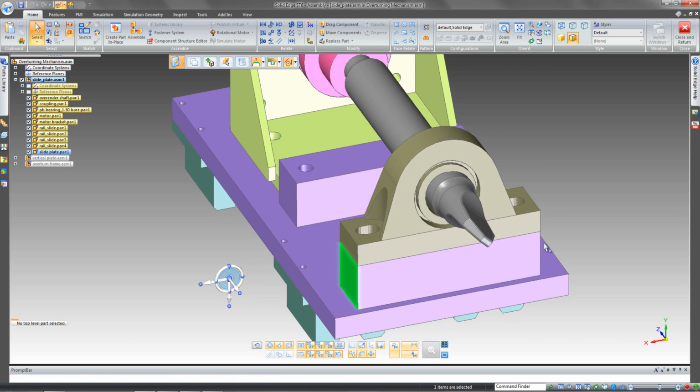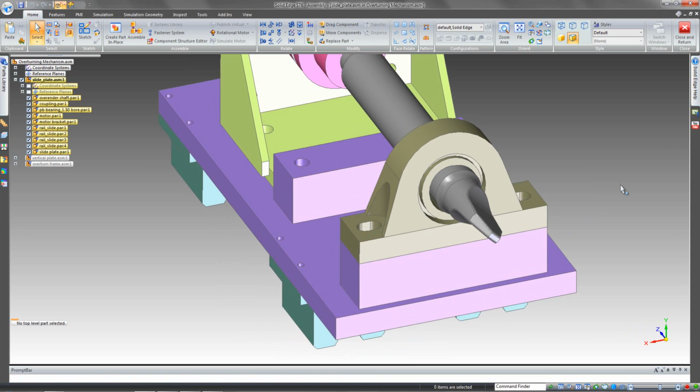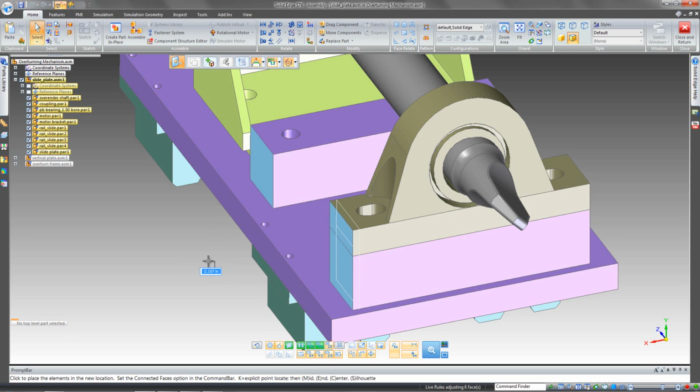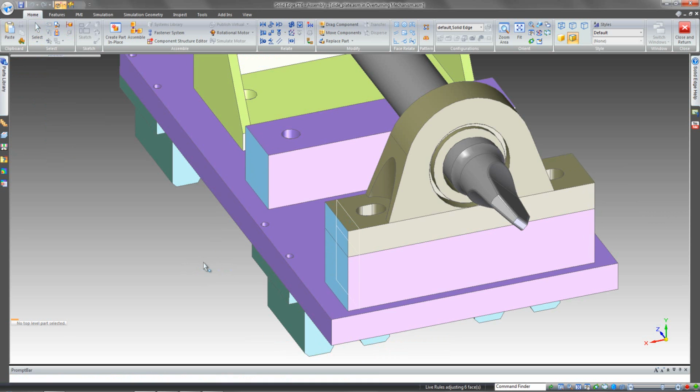As I mentioned, as I modify that purple component, I also need to make a change to this bearing that sits on top of it. So what I can also do is select, and again I can hit spacebar to add more faces. I can select the face on that component as well. And I'm going to move the steering wheel just for clarification so we can see what's going on. But you'll notice that now I can change the faces on that bearing at the same time. So again, I'm modifying multiple components at the same time.